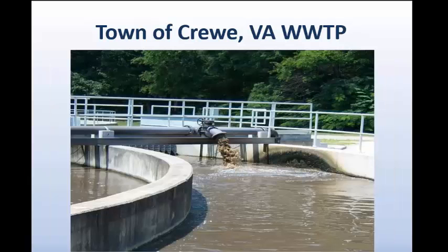Now this is not a picture of our facility, but this is one that represents exactly the issue that we were dealing with. We had our return activated sludge discharge piping discharging above the water surface, or the mixed liquor surface, in our anoxic zone channel. We also had the introduction of our influent, the water entering the plant, discharging in the same zone several feet above the surface of the channel.